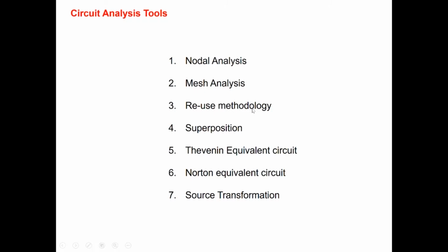And then we looked at a technique based on reusing results that had been derived and verified earlier, results like series and parallel equivalent circuits, current and voltage division, delta-Y transformation. Then we had looked at a technique called the superposition principle, whereby we could evaluate the response of each independent source separately and then add up the results to get the total response.